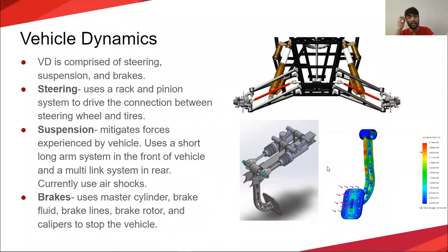We do a lot of testing. We fabricate most of our parts except for brakes, which we tend to outsource. But we do a lot of testing, whether it be actually driving the car around and doing strain gauges, or doing static testing of seeing how the suspension and the steering react when you're going through bumps and droops.